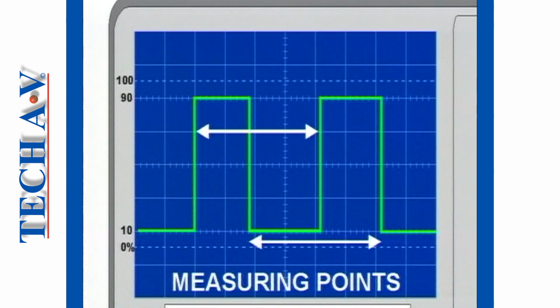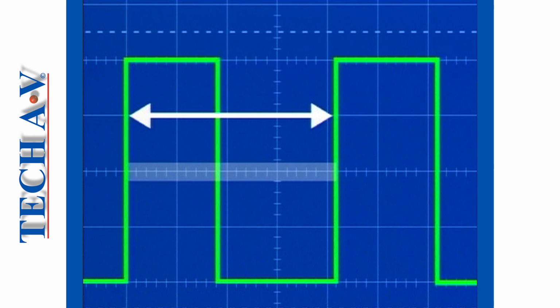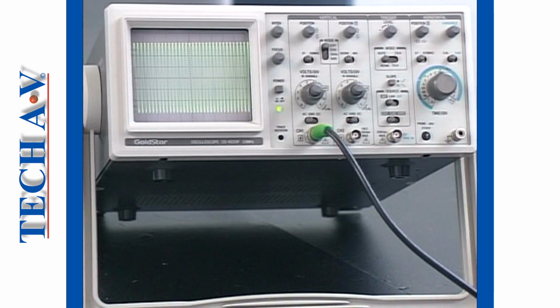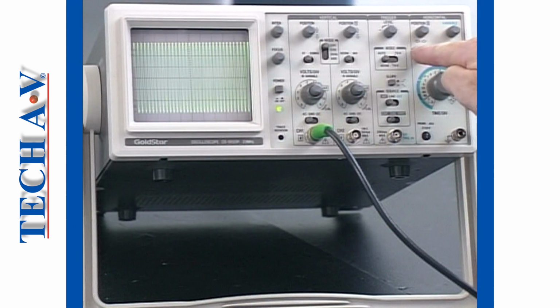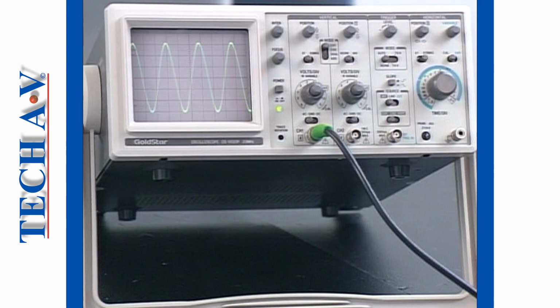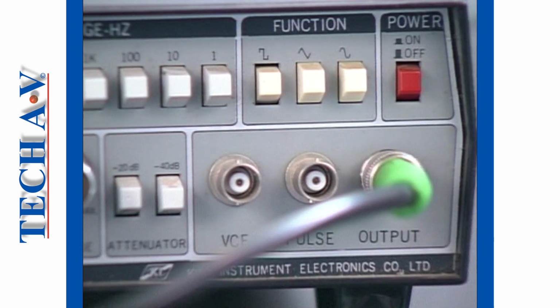Remember that time measurements can be made commencing at any convenient point on the waveform, as long as the time taken to complete one full cycle is accurately measured. Use the subdivisions on the center graticule line to assist in making an accurate measurement of time. When very high frequency signals are analyzed, the horizontal magnification switch is used to stretch the signal so that it is clearly visible on the screen. With these points in mind, let's calculate the frequency of this triangular waveform.